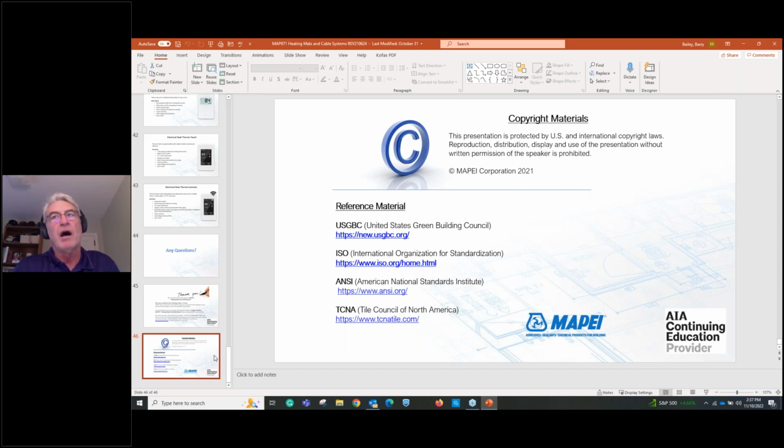Definitely a hollow floor, you would want to repair that. You would want solid contact under there. The first thing is that you don't have enough coverage to begin with, so you really can't put a Band-Aid on that, especially if you're just guessing where it's hollow and we've got a heating element under it. You'd have to remove the tile and inspect and see what you have. I wouldn't recommend just shooting an epoxy injection under any hollow floor like that.